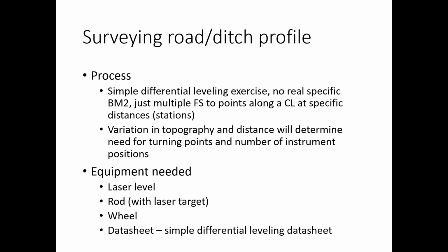We generally always have a specific benchmark which we start out with. Sometimes it's a point of known elevation, or it's an assumed point of elevation, or just essentially a starting point. So it can all be relative to itself. There may not be an actual elevation above sea level, but it's all relative to each other.